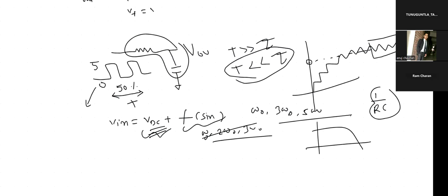So these values it will give me at steady state. It should give me an ideal steady state of DC value, but it is giving some ripple. The reason for the ripple is that some sinusoid frequencies are also coming in this range. So even around the DC value, it is trying to reach the DC value, again it goes a little bit low, and such ripples you can see.